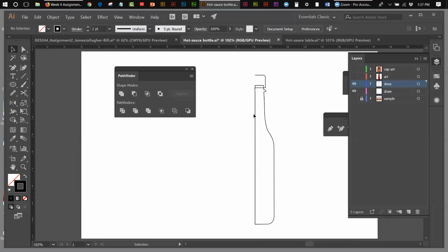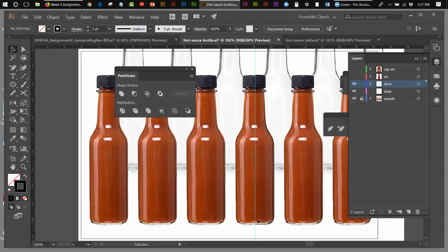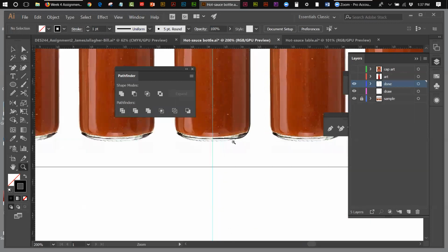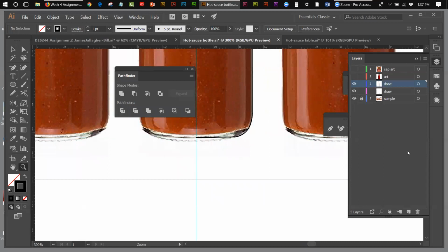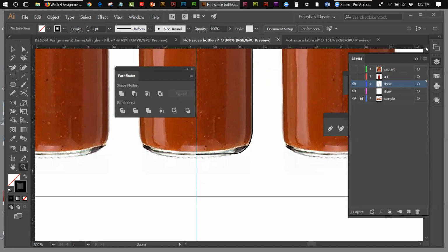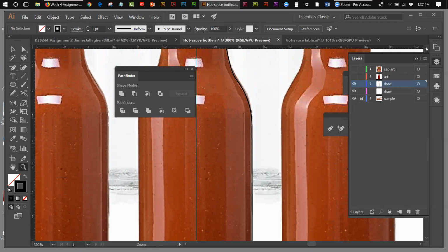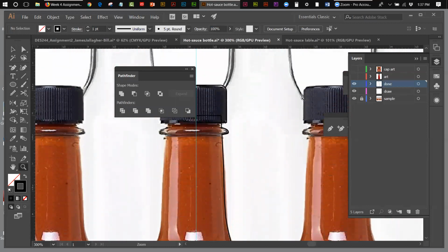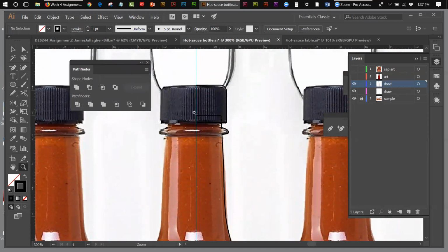Okay, now watch, I delete this, and I have my open shape, one continuous open shape, my main bottle shape. Now I noticed something, and it looks to me like this. Let me just check this position here. I want to make sure that my line, yeah, that looks pretty good. I'm making sure that my line goes properly to my guide, and I'm going to do the same thing up here. I want to see whether my line goes properly to my guide, and it actually looks like it does.